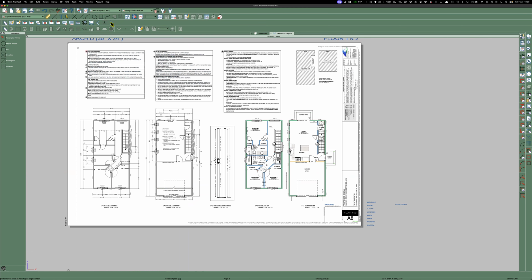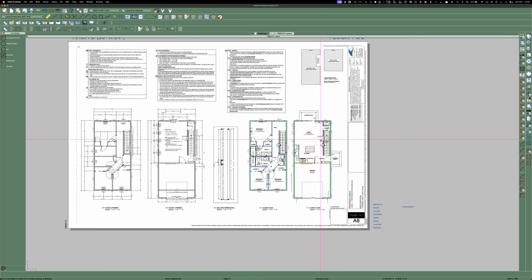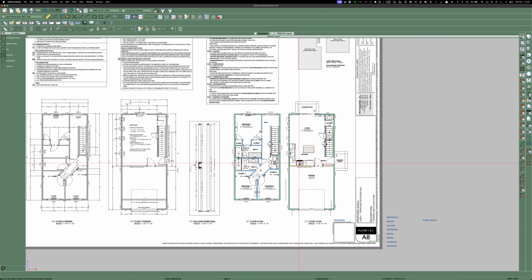All right. Here's the plan views. Here's the floor framing. In my wall framing on the first and second floor is where I put all my dimensions, just because it seems like that's what the framer wants to see, and it's to the face of framing. And then on the plan views, I put in all the kitchen appliances and cabinets and all that stuff with no dimensions so that you can just look at it and get a flow for it.